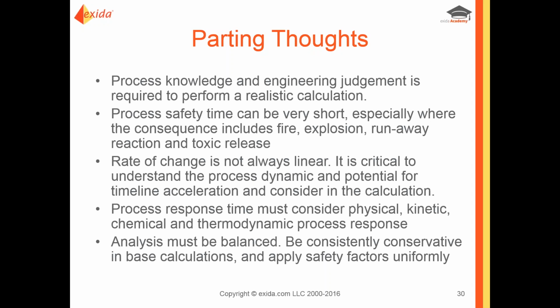If that's something that is significant, then we should always consider those part of just getting to the time to trip. You've got to take those delays into account, and that may be an additional factor that you need to consider to adjust that safety response time. Just add another variable to that equation to take into account that additional delay.